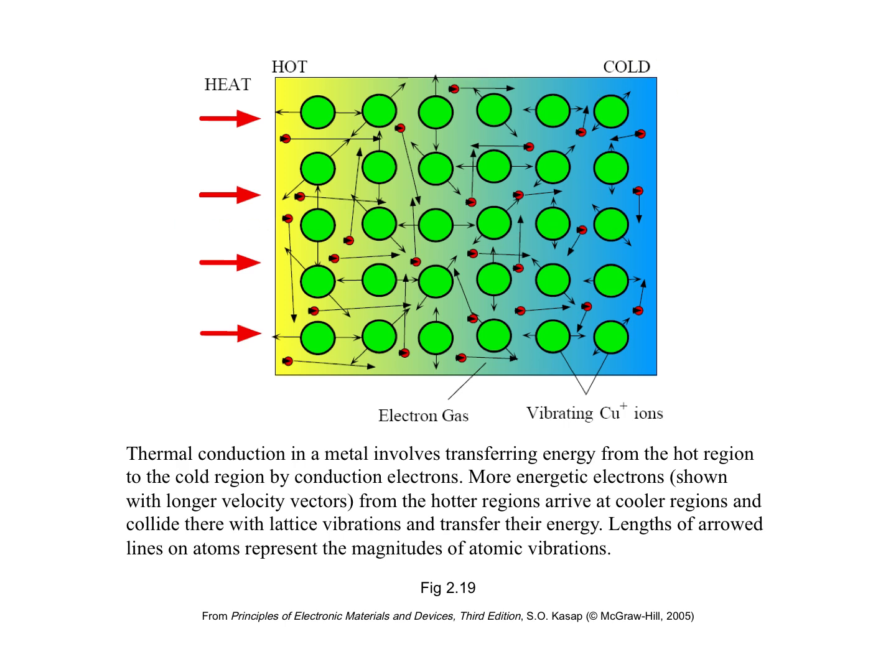Thermal conduction in a material involves the transfer of energy from the hot side to the cold side, either by these vibrating atoms or the transporting electrons. The vibrating atoms on the hot end move slightly faster than those of the cold end. Also, the electrons that can transport also move slightly faster at the hot end rather than the cold end. Thus, when the atoms or electrons collide with one another, they generally move energy from the hot side to the cold side. This transfer of energy from the hot side to the cold side is known as thermal conduction.